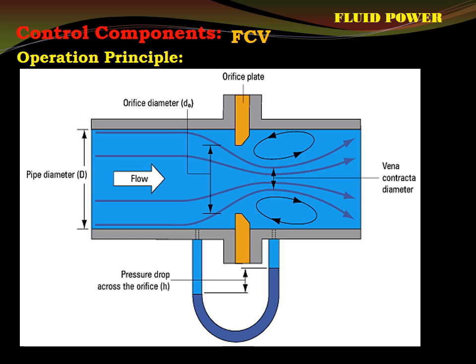And you can recall, usually pressure measuring devices are fitted upstream and downstream of the orifice, where we can find the difference in pressure by using a differential manometer. So if we can measure the pressure difference across the orifice, we can find out the flow rate through it